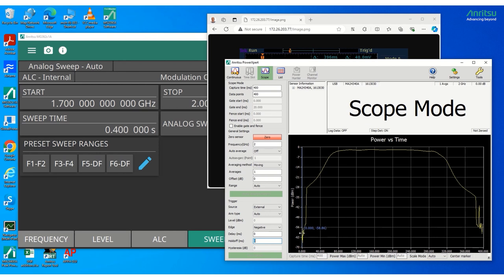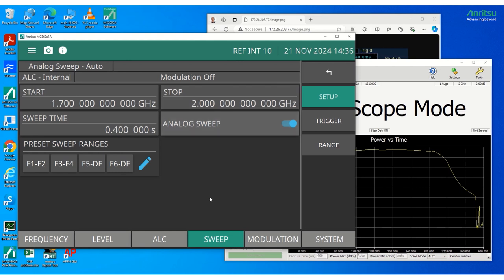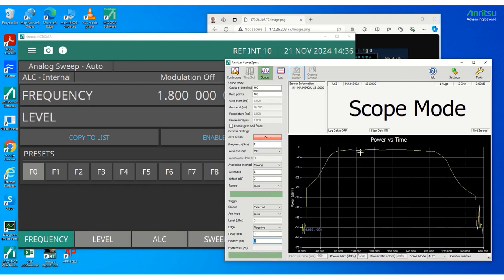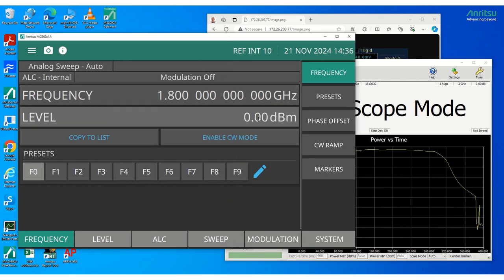And remember, we have set the output power to, let's go back to the Rubidium signal generator GUI. We have set the output power to 0 dBm, and with 0 dBm you have some loss here, maybe 2 or 3 dB loss, and then the stop band is almost 50, maybe 55, 56 dB. This is the dynamic range you are getting in this measurement, and you could get much higher dynamic range if you increase the input power.